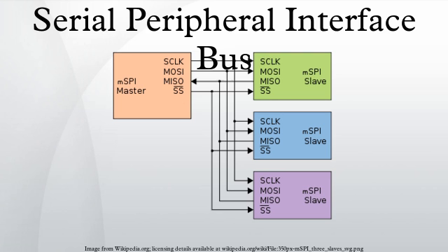In a performance-oriented design or a design with only one ESPI slave, each ESPI slave will have its alert pin connected to an alert pin on the ESPI master that is dedicated to each slave, allowing the ESPI master to grant low-latency service because the ESPI master will know which ESPI slave needs service and will not need to poll all of the slaves to determine which device needs service.